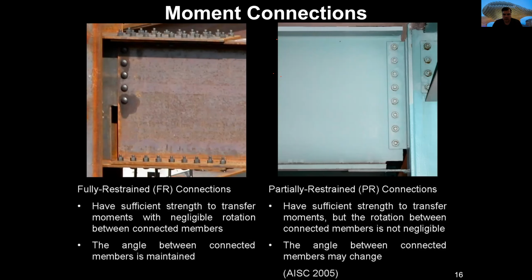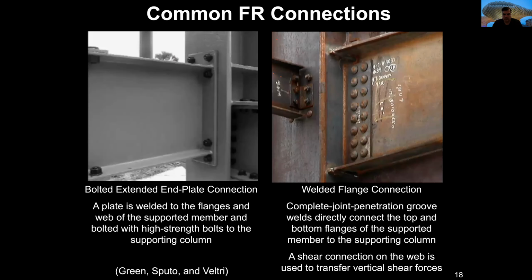This is enough to transfer moments, but there is some kind of rotation in the superior part. We have here a bolted stem plate connection. What is that? We have a plate, that is this element here. That plate has been welded to the I-beam in all this area, also the other side, obviously.